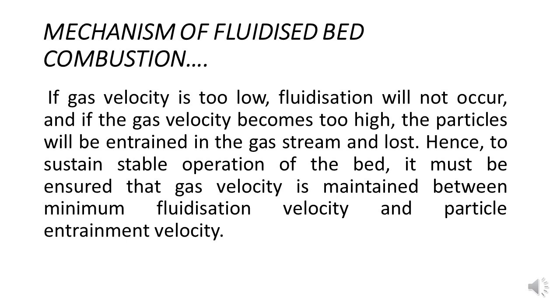Now, the mechanism of the fluidized bed: if the gas velocity is too low, the fluidization will not occur, and if the gas velocity becomes too high, the particles will be entrained in the gas stream and lost. Hence, to sustain stable operation of the bed, it must be ensured that the gas velocity is maintained between the minimum fluidization velocity and the particle entrainment velocity.